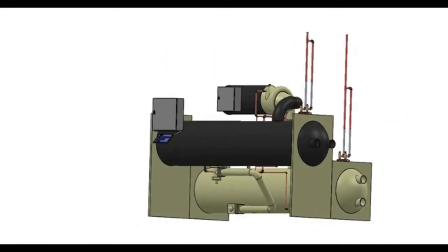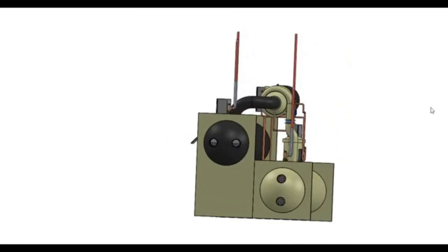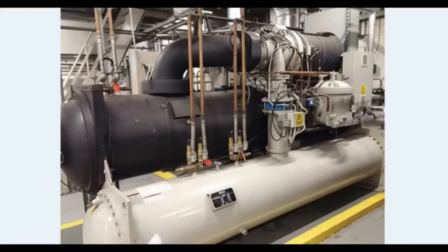So you should have written down the 4 main components and the 3 main circuits within every chiller. So I'd like you to now test yourselves. If we bring up this photo here of a real life chiller, the McQuay chiller, and just apply your knowledge here. So take a few moments. Can you tell me what is this cylinder here? Remember, it's got a tube, it's being fed refrigerant off of the compressor, and it's coming down and entering the condenser.